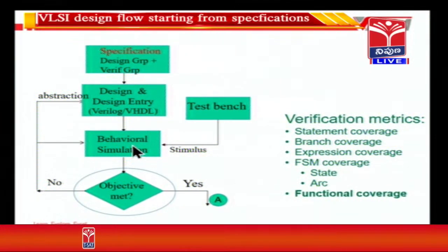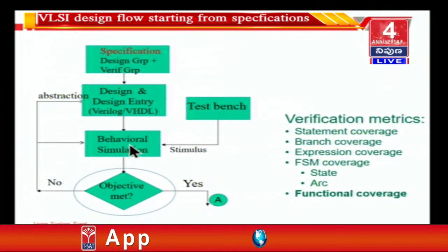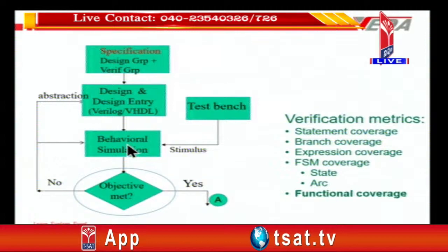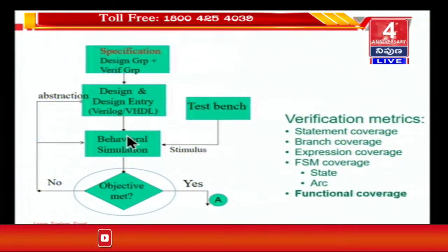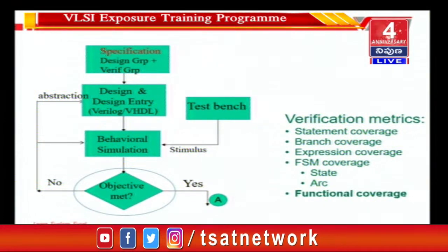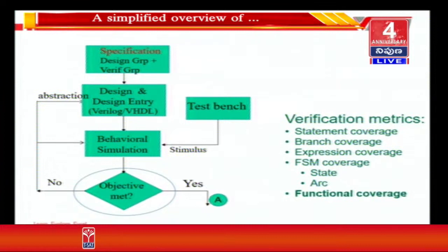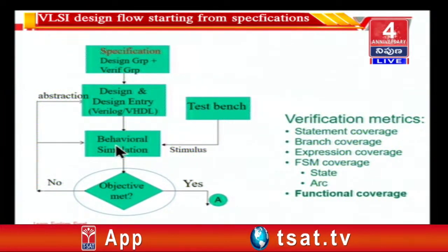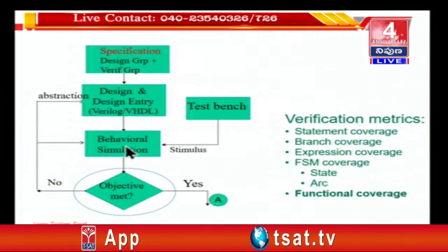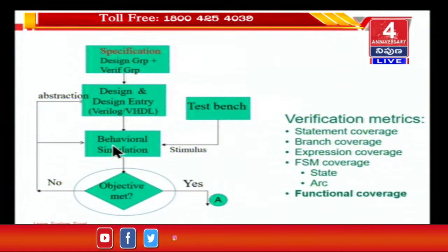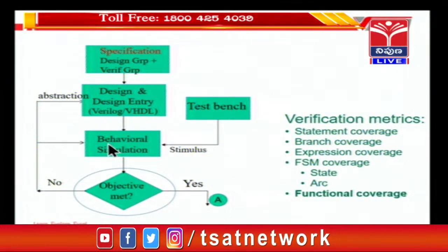Simulation is running in software a model which mimics or captures the functionality of the block that is supposed to be there after the block has gone into silicon. That is simulation, completely running in software and capturing in software and verifying in software the behavior of that block that would exist after it has been manufactured.